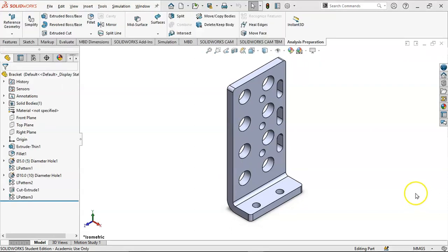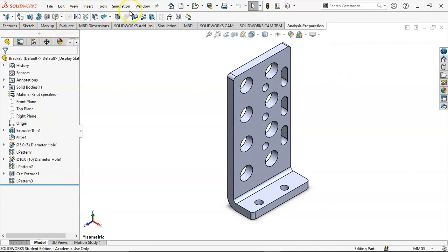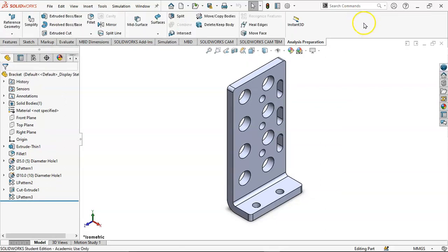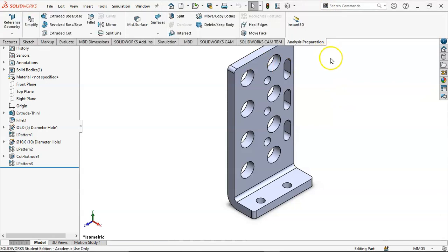Now, what I'm about to show you are things that change with each version of SolidWorks. So, in the 2020 version, you right-click here, and you can use large buttons with text, and it minimizes the command manager. Right-click again, enable large buttons with text. Right-click again, disable the command manager altogether, and it collapses completely. Right-click in the top bar, and you can enable the command manager, so it comes back.